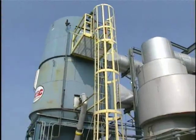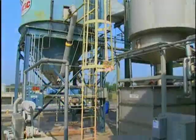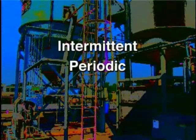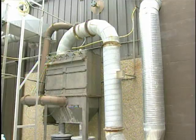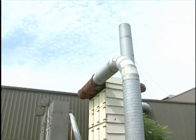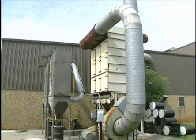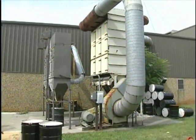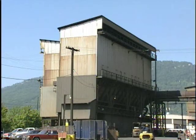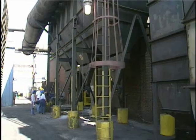Another way of distinguishing between different types of fabric filter collectors is based on the way they operate. The three modes of operation are intermittent, periodic, and continuous. Intermittent collectors are used on processes that operate intermittently. When the process shuts down, the collector goes through a cleaning cycle and then shuts down and waits for the next processing cycle before starting up. Most intermittent collectors clean by shaking, but could also clean by reverse pulse.